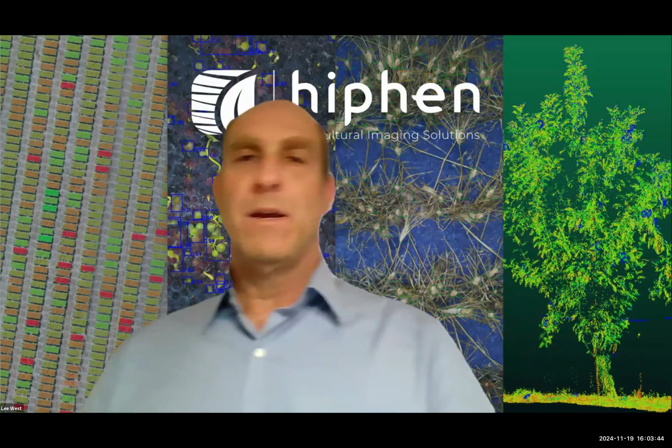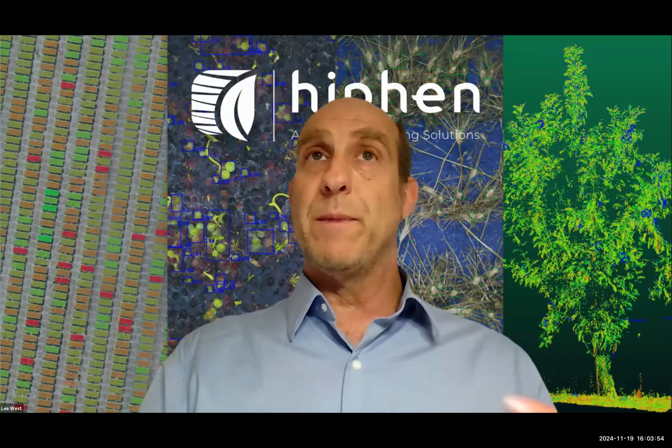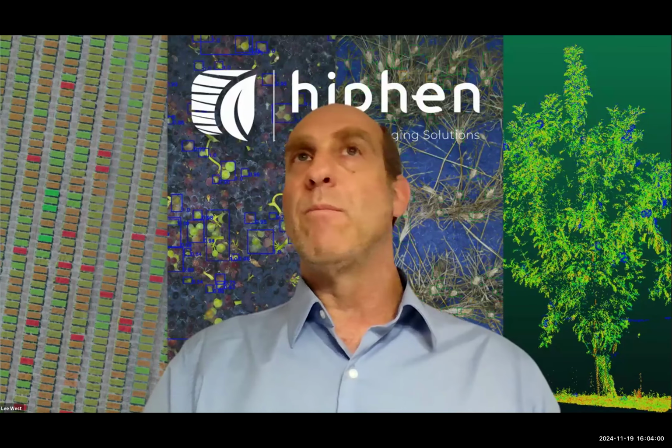How do you decide flight height for different crops and for different phenological stages from early to late maturity? So we're generally trying to figure out exactly what trait we're looking for. If we're doing things like vegetative indices, we can fly at pretty high altitudes. But if we're looking for sunflower counts or sorghum head counts, or maybe even harder, things like tassel counts on maize, we need more resolution.